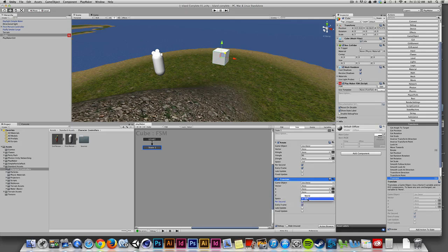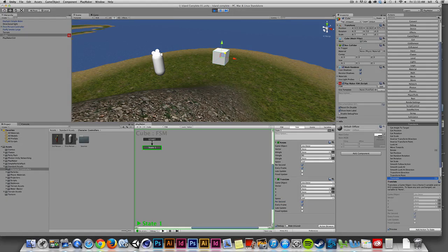And there's two different options here. We can translate or rotate or move an object based on its self position or its self axis, or we can change this to its world axis. Now I'm going to leave this set to self for now, just so we can see what happens. And I want to cause this to translate along its own z-axis on itself, so on its own z-axis, per second every frame.